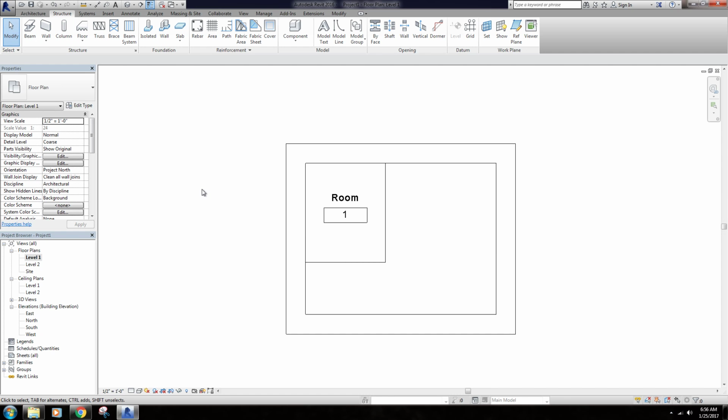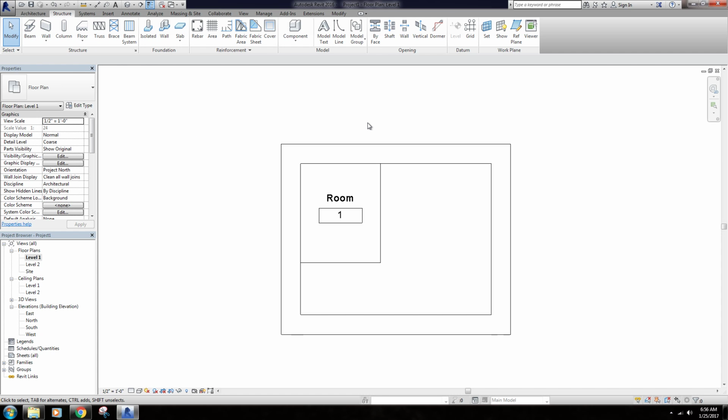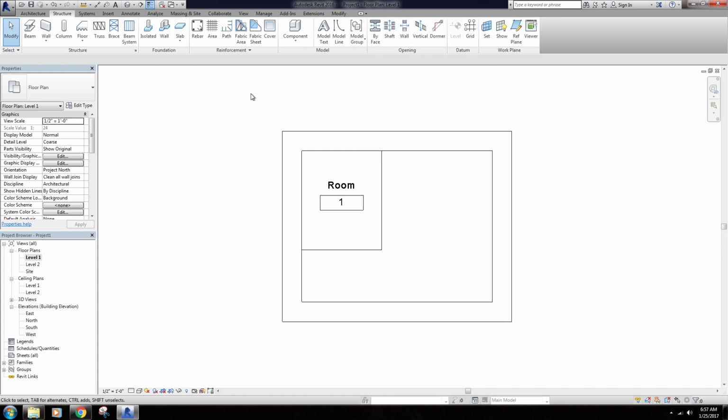So if you built your entire structural element that had bracing, beams, columns, that sort of stuff, and then pretty much the skin of your model was a curtain wall, you could go through, hide pretty much everything but your structural elements and see just a 3D view of the structure of your building. If that's a view that you think you're going to need in the future, go ahead and put that stuff in. Most times I don't really deal with this sort of stuff all that often.